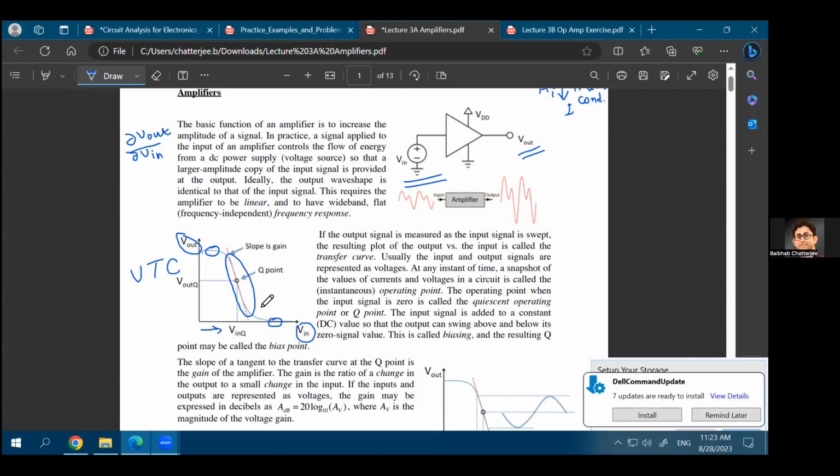Okay. What does that mean? That means that if you apply a small AC voltage, let's just assume, exaggerating things, that this is 0 to 100 volts on the left axis, the y-axis, and 0 to 100 volts on the x-axis. For the first 10 units, you don't see any change in the V out. You don't see any kind of gain. Where do you see the gain? When both the input and output voltages are near the 50% points. And again, when your input voltage reaches the 100% point, its maximum voltage, you don't see any gain again.